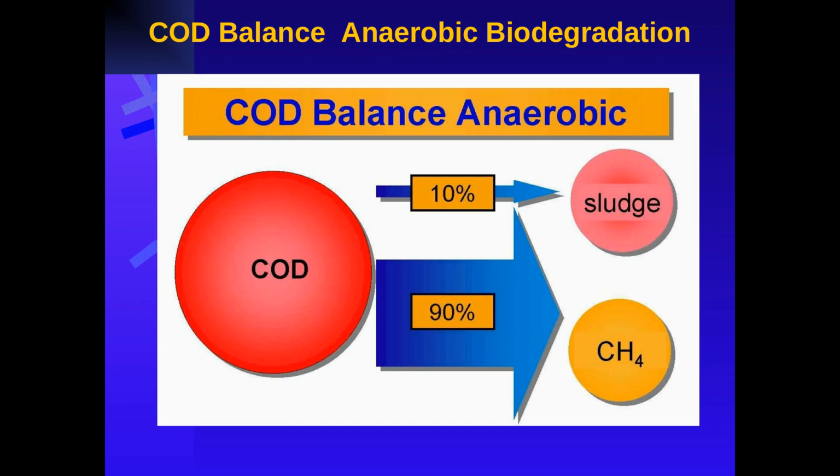The benefits of anaerobic treatment extend further. The granular sludge developed in high-rate anaerobic reactors has excellent settling properties, allowing for high biomass retention and efficient treatment. The process is also resilient to shock loads and can be operated intermittently without significant loss of performance. Finally, the enclosed nature of anaerobic reactors minimizes odor emissions, making them a more environmentally friendly option.